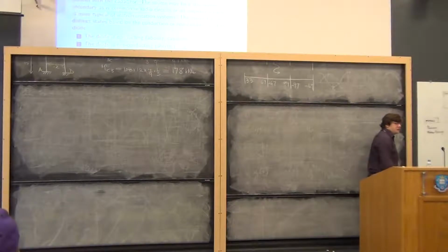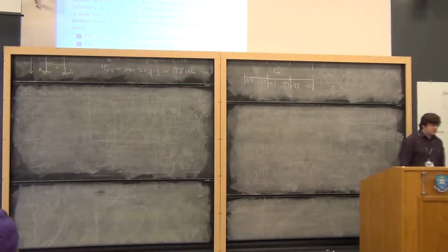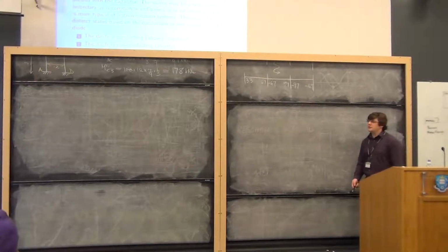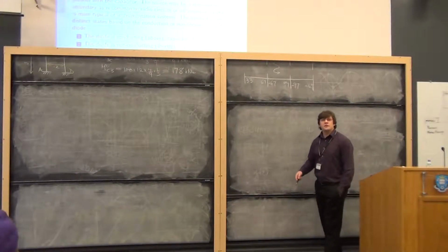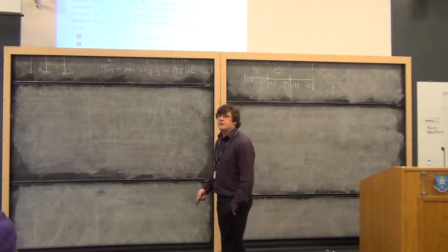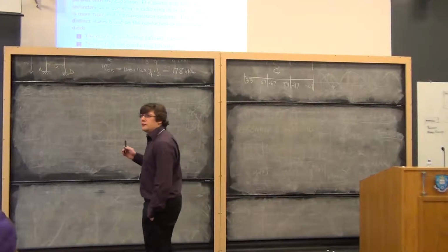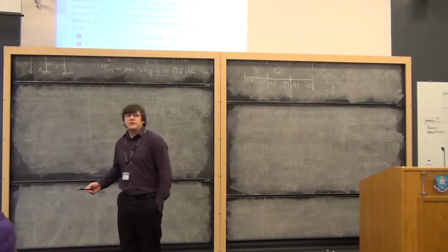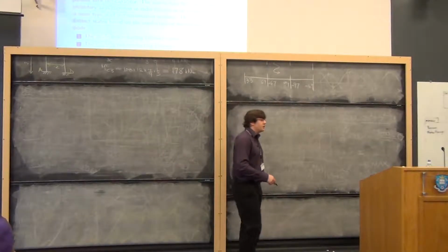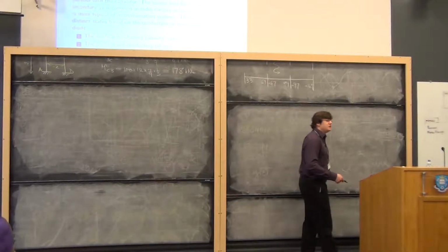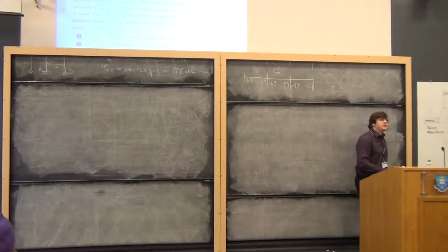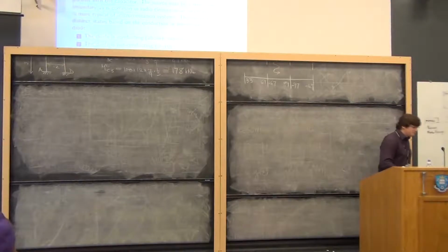And the circuit's got 2 distinct states. I should really say it's got 3, but the diode's got the 3. It's either conducting, or it's on the point of conduction, or it's not conducting. But the circuit I want to discuss is only the 2. It's the bit where the diode is on and the bit where the diode is off. Because when the diode's on the point of conduction, not much is actually changing. Stuff will be happening in the circuit, but nothing major will be worth talking about.